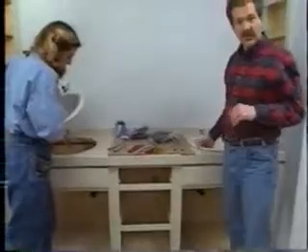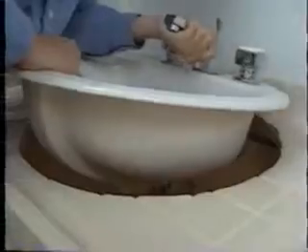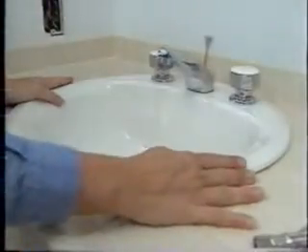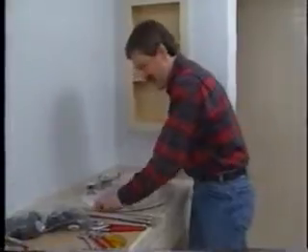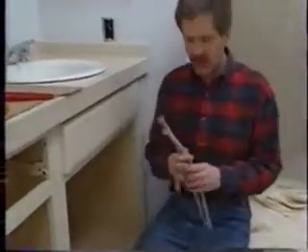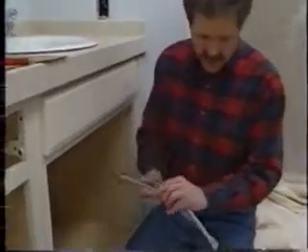These are self-rimming sinks, which means they sit directly on top of the countertop. They came with a template that helped us cut the openings to the right size. Now we're ready to hook them both up to the plumbing. We'll start with the supply lines, which means hooking up the faucets to this flexible tubing with a 1/2-inch coupling to the faucet and a 1/4-inch coupling to the shutoff valve.